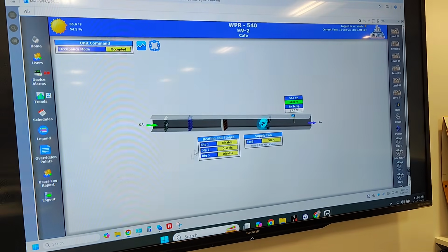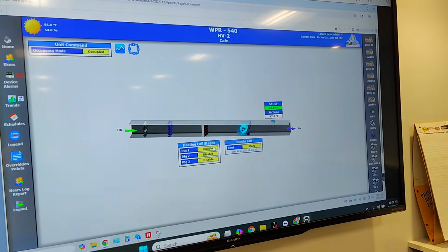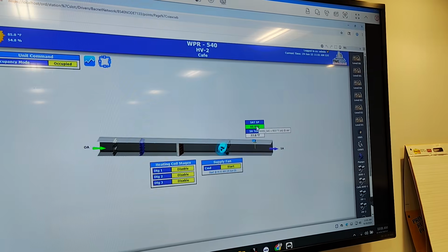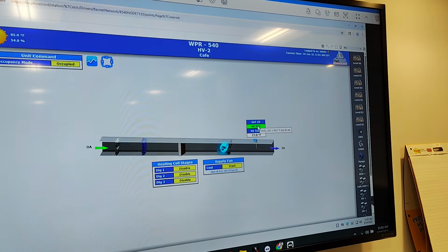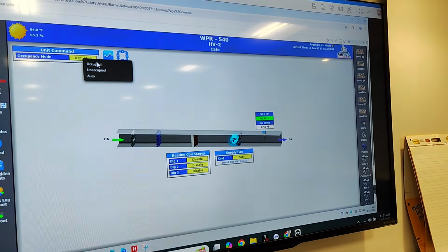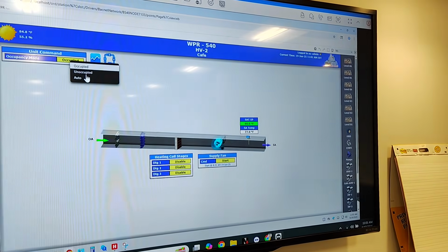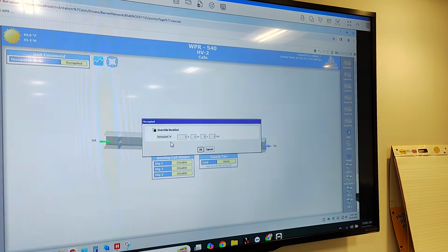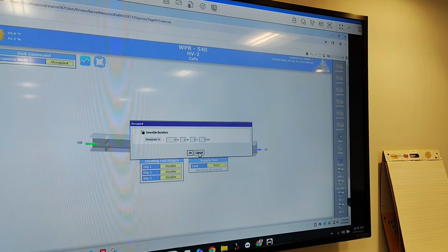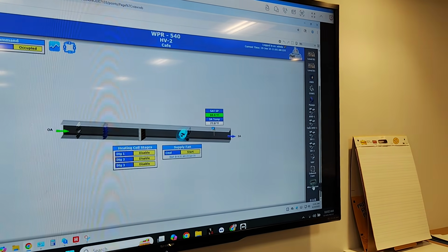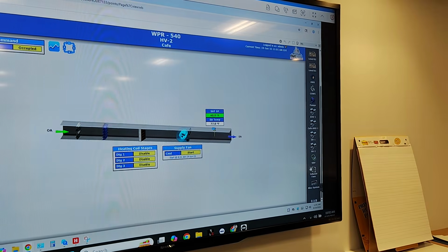So you have heating coil stages, supply fan, and the set point. Same occupancy mode: occupied. For occupancy mode, you right click. You can do occupied, unoccupied, auto. Same thing. Occupied, you can check the duration. And HU2 is the same. Then VAVs we don't have for now.